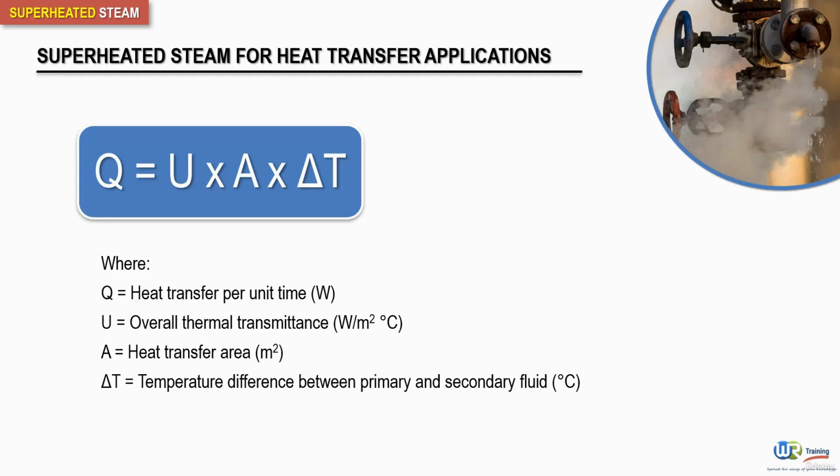If there is no choice but to use superheated steam, it is not possible to maintain steam in its superheated state throughout the heating coil or heat exchanger, since as it gives up some of its heat content to the secondary fluid, it cools toward saturation temperature. The amount of heat above saturation is quite small compared with the large amount available as condensation occurs.